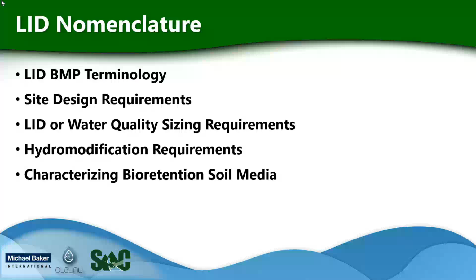bioretention soil media design such as depth, infiltration rate, and composition is a key part of bioretention and biofiltration functionality. However, since bioretention soil media terminology and requirements have been established independently across the California Water Regional Boards, different specifications and different terminology have been developed in the different regions.